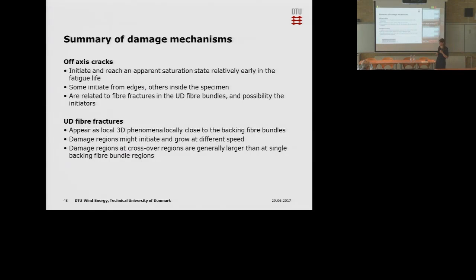So to summarize the damage mechanisms I've mentioned throughout this presentation in relation to the off-axis cracks, it was found that they initiate and reach an apparent saturation state quite early in the fatigue life. Some initiate from the edges, and others initiate away from the edges, in the center of the specimen.